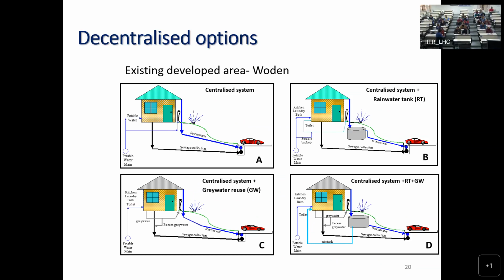And if you provide it more, initially in the upstream, then it will have an effect further in the network. You have to take the invert level of that pipe deeper and deeper. So again, there is economics that plays into whether it is okay to flush only a few critical pipes, or you design your whole network significantly deep, which will have a greater impact on the overall cost of the system.